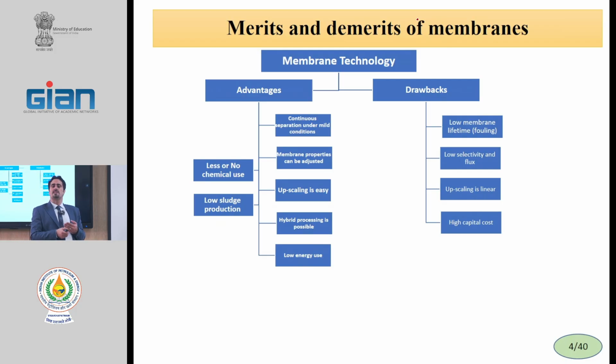Or for reducing the fouling, we must wash the membranes. For example, in dairy industry, we wash every day the membranes because the protein of milks can attach to the membrane surface and cause fouling. But in reverse osmosis membranes, we usually wash the membranes every 3 months.